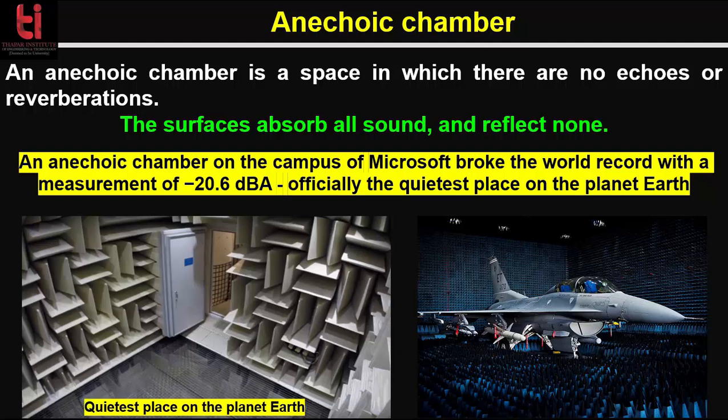Now the question is why we actually need them. What are anechoic chambers used for? Anechoic chambers are typically used in acoustics to conduct research. All sound energy travels away from a noise source with almost none reflected back. Typical anechoic chamber experiments include measuring the transfer function of a loudspeaker or the directivity of sound radiation from industrial machinery. You can see here an F-16 Fighting Falcon in an anechoic test chamber.